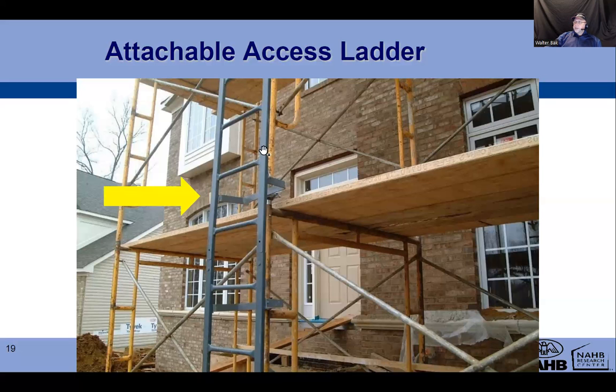All right. Now, yes, sometimes they're available, those attachable access ladders. They are being used to climb on and off the platforms of the scaffolds. Again, do not use anything else but whatever equipment is provided for us to access the scaffolds area. All right, do not climb the cross braces.